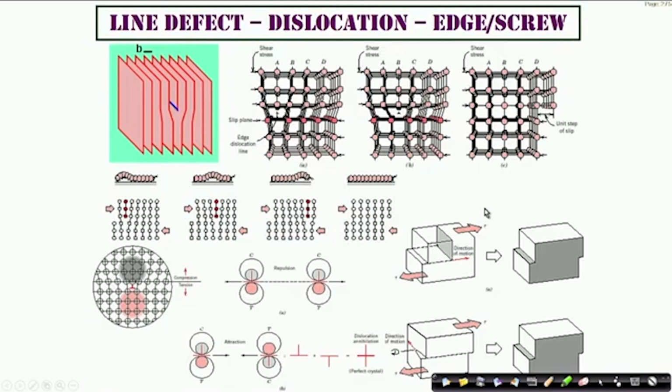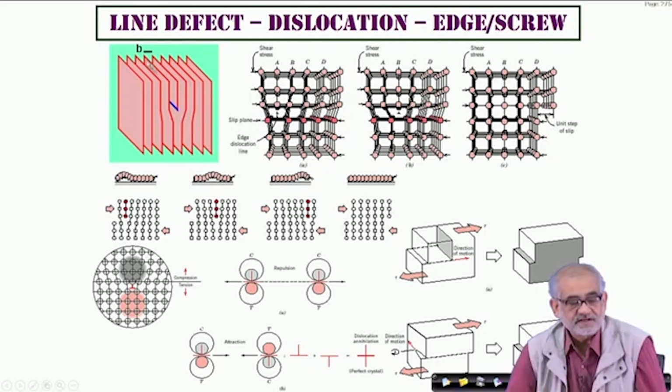So far we talked only about the point defects. Now what if you imagine a situation that we have these kind of planes which are equidistant because they are part of a crystal where we have long range periodicity, and for whatever reason if we also happen to discover an extra half plane introduced in between, sort of squeezed in between, then if you create a Burgers circuit, or if you define a circuit around this kind of a situation where you have both a defect and a non-defective lattice, let's say you start from here.